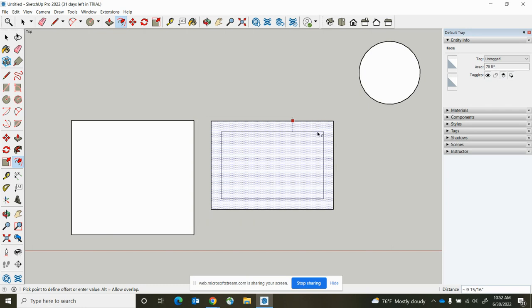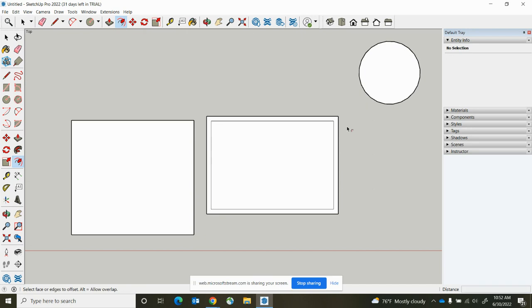So let's say I wanted to create walls for this space. And the dimensions I were given were interior dimensions, I'm going to go outside. I'm going to do 4.5 inches for 4.5 inch walls. And now I've created that line. Okay. In SketchUp, what it's done is I have a shape here and a shape here still. Okay. So this is not hollow. This is a surface that's there. So I just want you to be aware of that as you go through.